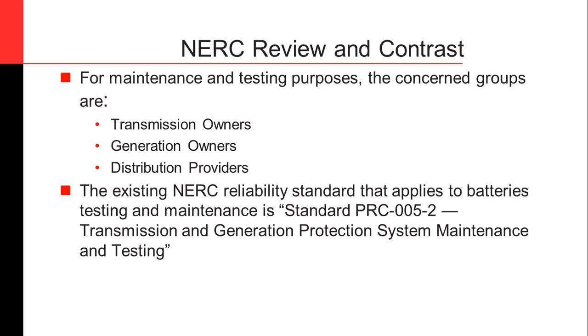It's actually based on what the manufacturer defines as a complete cycle. One manufacturer might say 80% depth of discharge is considered a full cycle. So in that instance, yes, 50% would not be half; it'd be about 60% of a cycle, give or take. Whereas if a manufacturer said 100% depth of discharge is considered a cycle, then yes, the 51% would be half of a cycle.